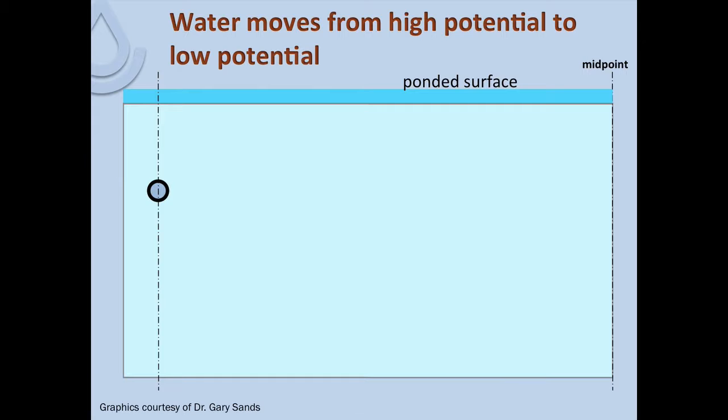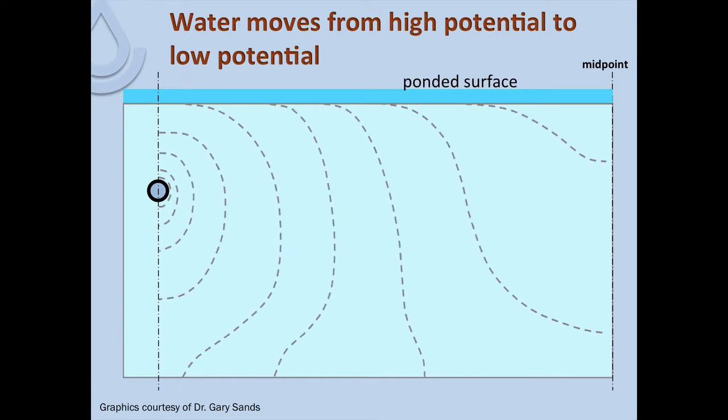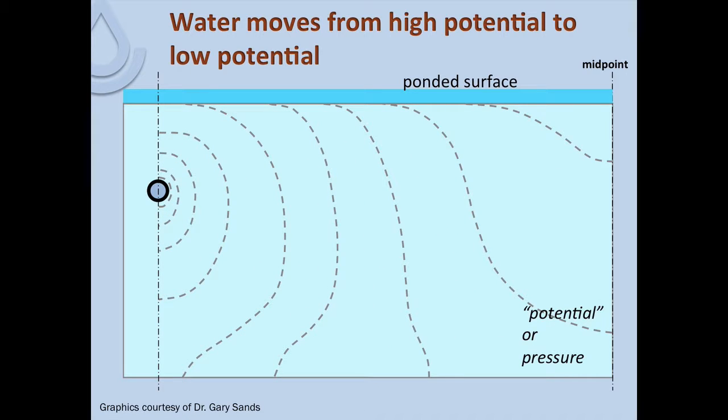Then as the water table comes up and builds up above the drain lines, we create positive pressure outside the drains just from the weight of the water building up on top of itself. The same way a scuba diver experiences more pressure the deeper he goes into the water, the higher that water table comes up above the drains, the more positive pressure we've got outside the drains.